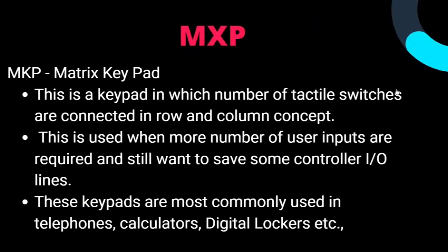We'll talk about the MXP, which is the matrix keypad. This is the keypad in which a number of tactile switches are connected in a row and column concept. It is used when a larger number of user inputs are required and you still want to save controller input and output lines. These keypads are most commonly used in telephones, calculators, digital lockers, and so on. Moving on.